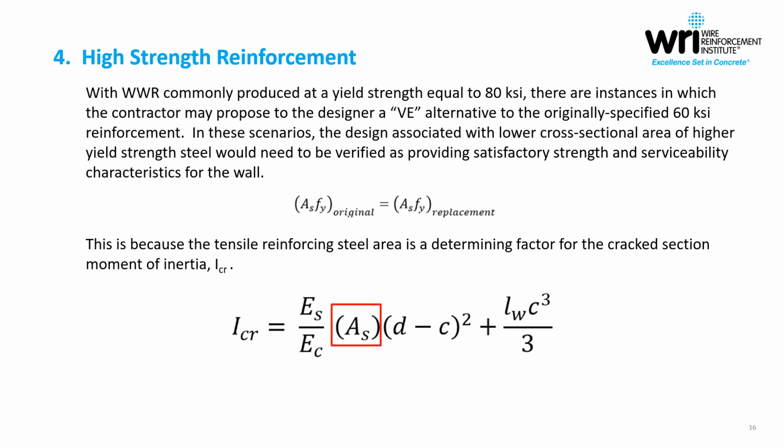Sometimes there are attempts to offset the effects of stiffness reduction that results from a reduced steel area. Engineers sometimes try to do this through an increase in the concrete compressive strength, but each case is different. The negative effect of a reduced cracked section moment of inertia must always be checked, given it can still outrun the benefits gained from a concrete compressive strength increase.